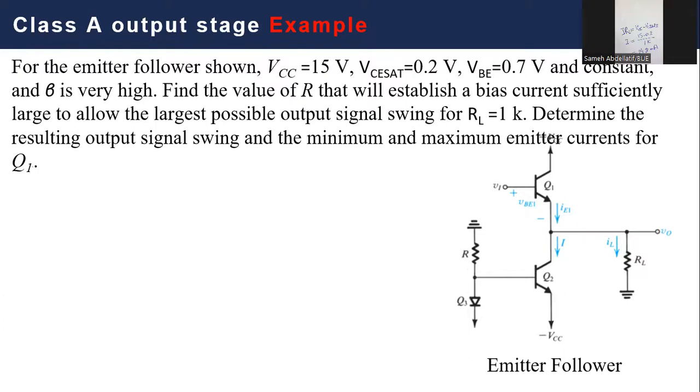What you can say is simply these pointers, let me open the pointer, sorry. Okay, so this point is negative 15 volts. So this point will be automatically higher by 0.7, which means that this voltage is negative 14.3 volts. So this is a determined node in the circuit. But you know, or you already know, that this is a ground.